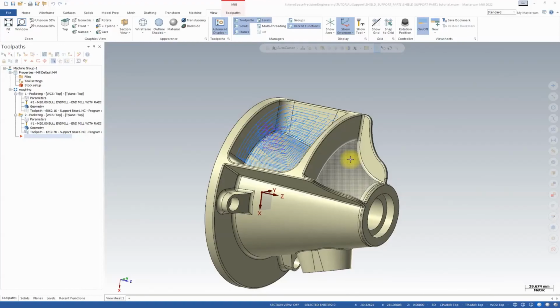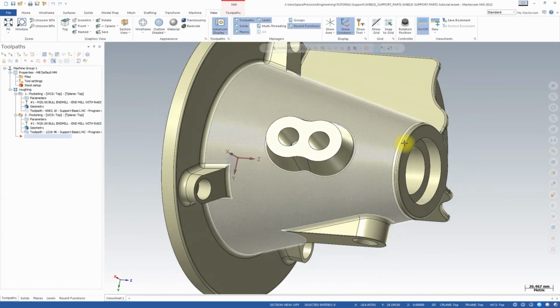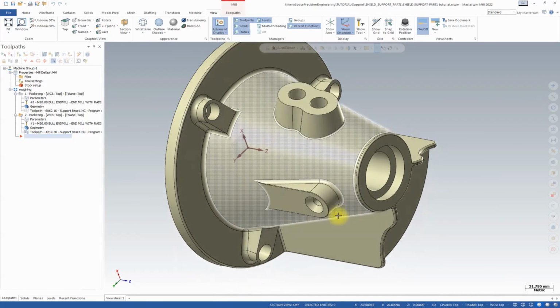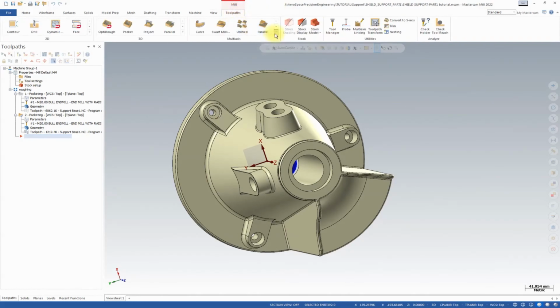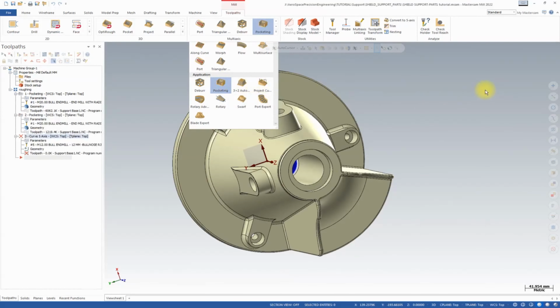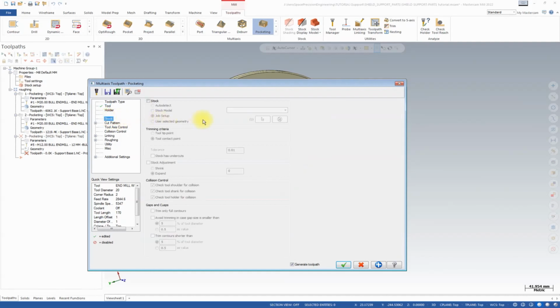Okay, with our next toolpath, you can see the pre-finishing of the taper wall. The tapered conical shape wall will be the pre-finishing toolpath. You can go to the toolpath, multi-axis pocket. Then select the tool and stock. Click the stock page.